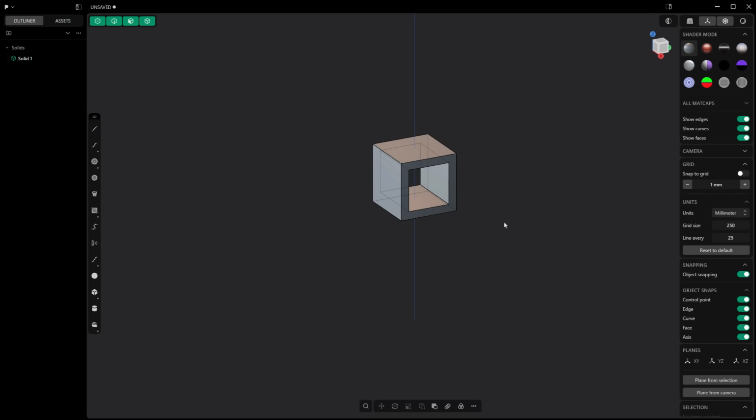Once you understand the basics of moving, rotating, scaling, duplicating, as well as Boolean, which again, these are Shift and D and Q on the keyboard. Once you understand these 5 right here, those are going to be very common tools that you use over and over again. So it's really important to try and commit those to memory, more so the move, rotate, and scale, but Shift D for duplicate and also Boolean.